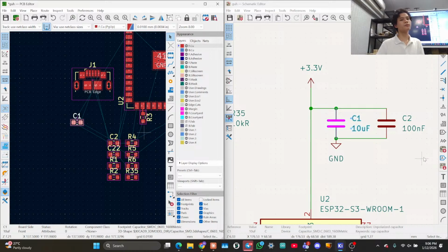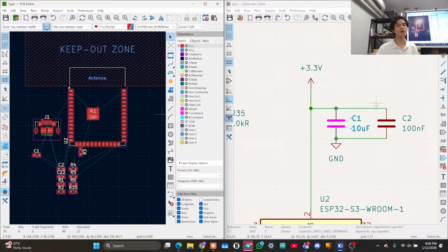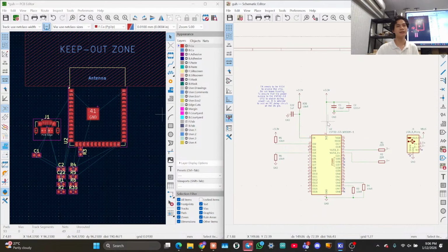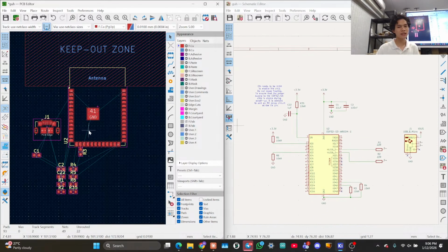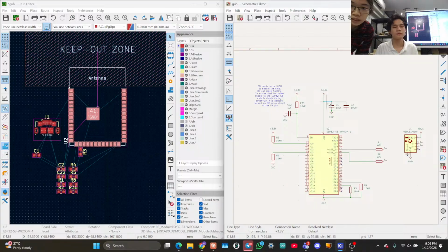So we split screen and we put the footprints, the layout editor, on one side and the schematic editor on the other side. If you click a component in layout, it will highlight it in schematic. You can also get pads. So for example, if you want to get the 3v3 net, you click this segment, press the wavy thingy next to the one.